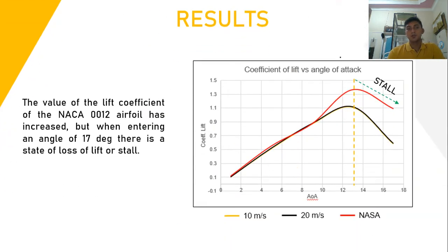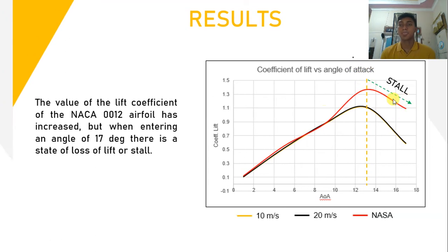We know that the lift coefficient of the NACA 0012 airfoil increases, but when entering an angle of 30 to 70 degrees, there is a loss of lift that we usually call a stall condition, here at 13 to 17 degrees.